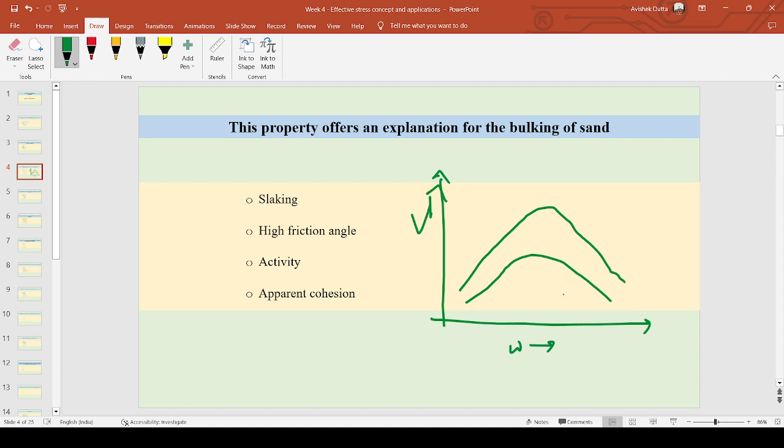For coarse grained sand and fine grained sand, the graphs go differently; bulking occurs in only sand. Now in this case there is an interparticle adhesion due to the capillary action of water, because of which on addition of moisture the volume increment occurs up till a certain level.